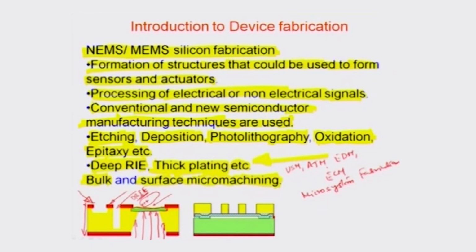So, this is another way of getting thin film pressure sensors, and this is also known as bulk micromachined pressure sensors. Okay. So, why it is bulk is because you are subtractively removing material from the volume of this particular wafer, and that is why bulk micromachining is a subtractive process. It is a material removal mechanism.